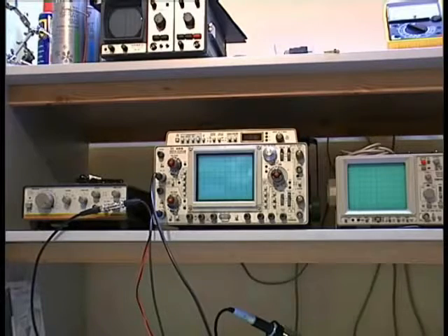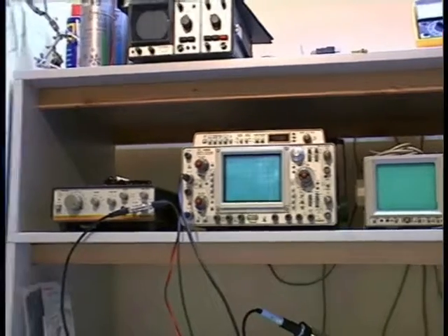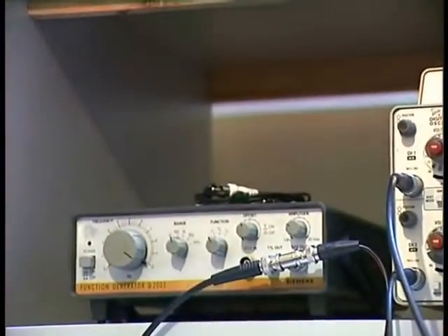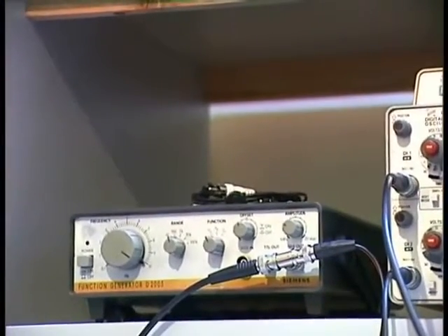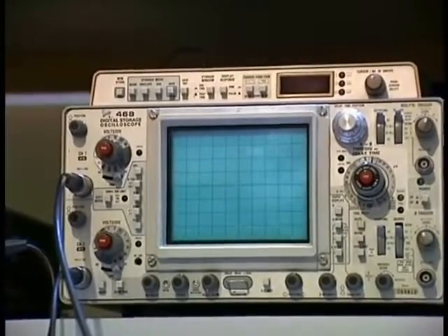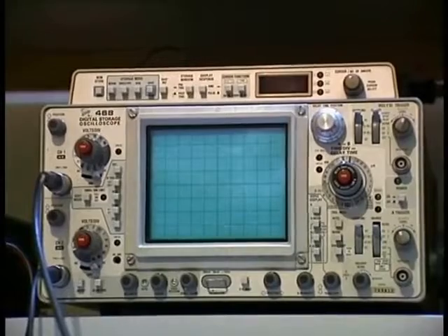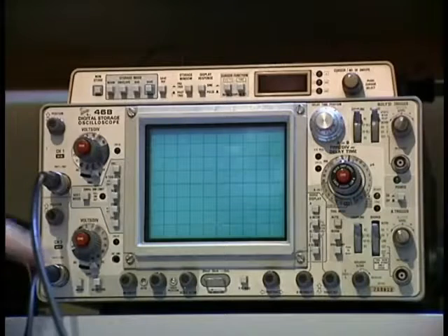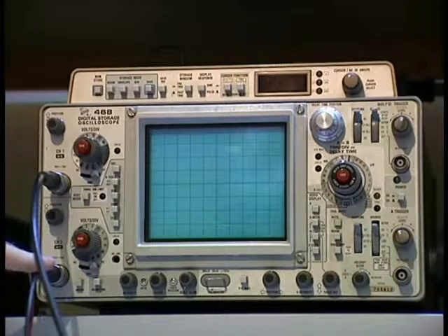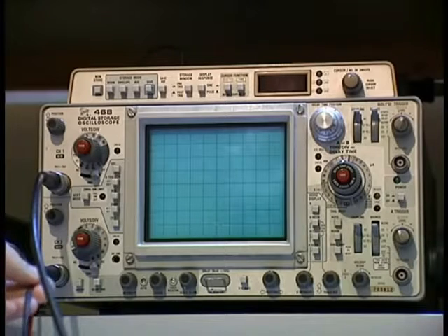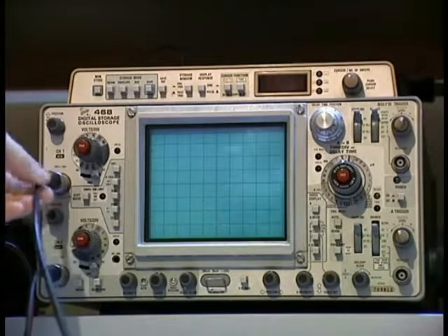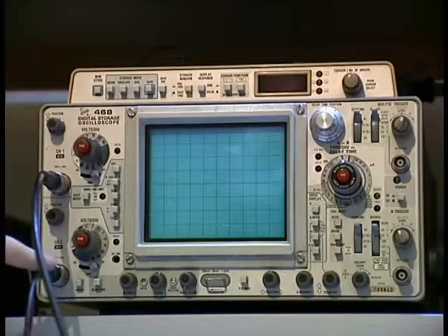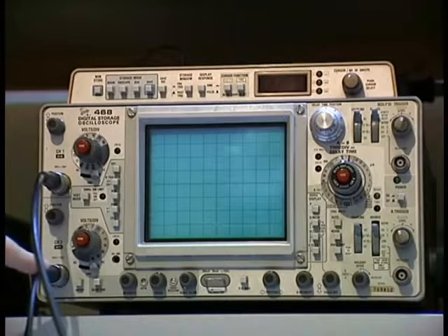So now we're taking a look at the scope. Here I've connected my function generator to the input of my circuit. It is generating a sine wave of about 1 kHz, and here I have the scope. As I have stated before, on the first channel, the upper channel, I have connected the function generator directly, and on the second channel I have connected the output of my circuit. This is a 10 times probe, and this is just 1 time, so this signal is 10 times lower than the other, because here we have a 10 times probe.